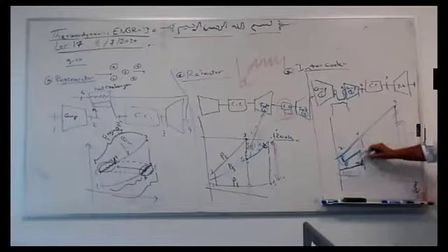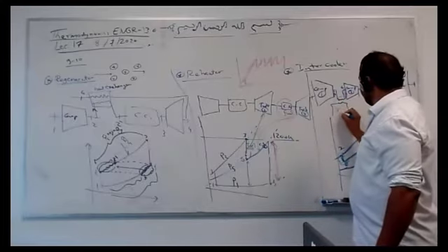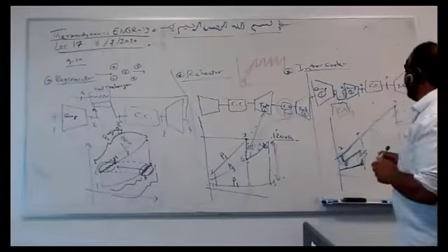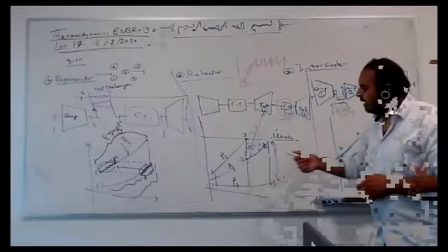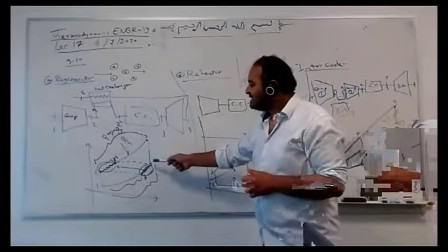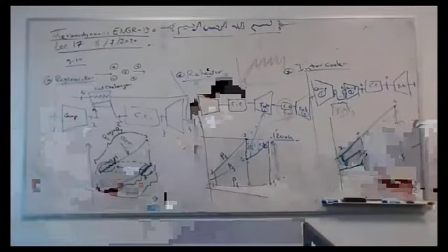If I compress directly, I will take less in the turbine because of this cooling. I pay less in the compressor. I reheat at the turbine. I used regeneration, I used some heat to warm up after the compressor.